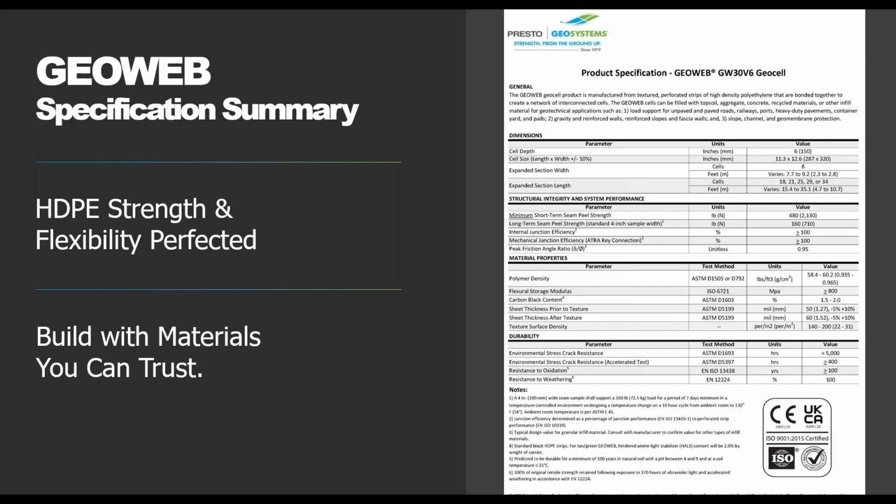To ensure the system really does perform well, I can't mention enough that we really do want to have really strong seams. That's both the factory welded seam, which are the internal welded seams, and the field joint seams. So those are the mechanical junctions that basically tie each panel together, whether that's end to end or side to side. So we use, like I said, that 100% virgin HDPE blend that we've been using for 40 years. It's going to last well over 100 years even if it's subjected to 24-hour direct sunlight. So it's really a long-term performance.